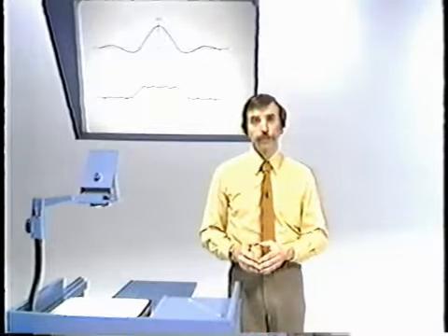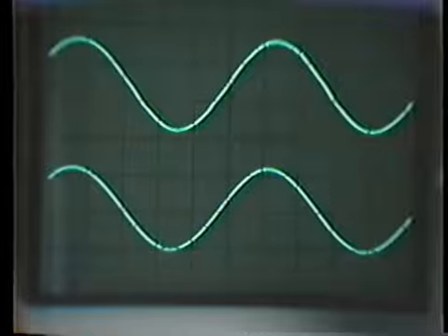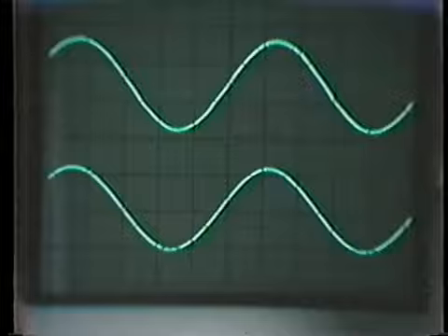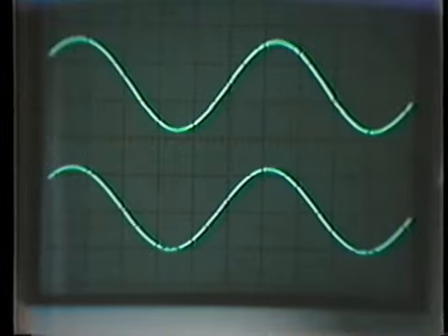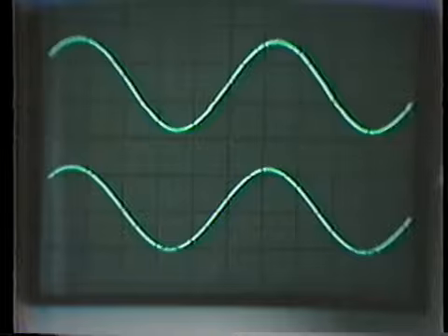So now let's look at the frequency response of the filter. Now what we'd like to illustrate is the frequency response of the equivalent continuous time filter, and we can do that by sweeping the filter with a sinusoidal input. So what we'll see in this demonstration is on the upper trace the input sinusoid, on the lower trace the output sinusoid, using a 20 kilohertz sampling rate and a sweep from 0 to 10 kilohertz, in other words, a sweep from 0 to effectively pi in terms of the digital filter.